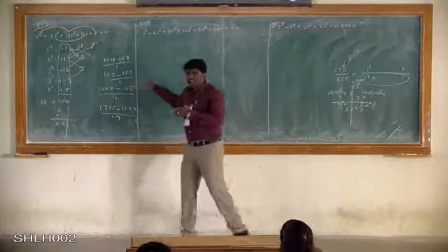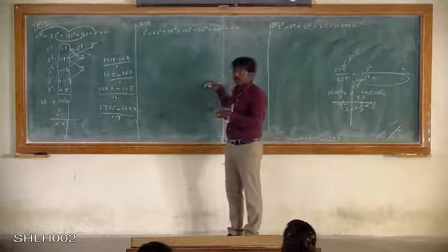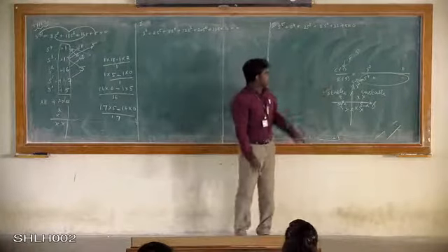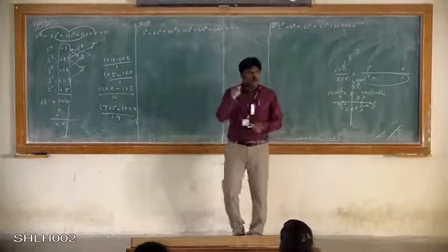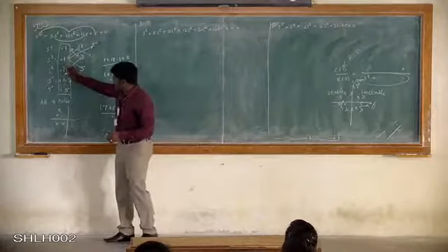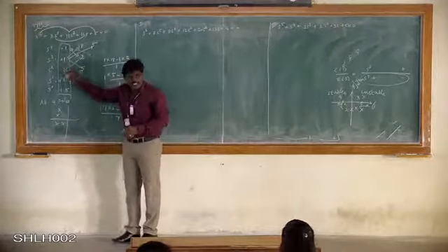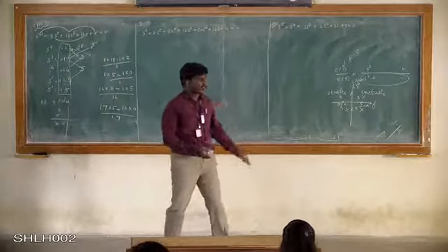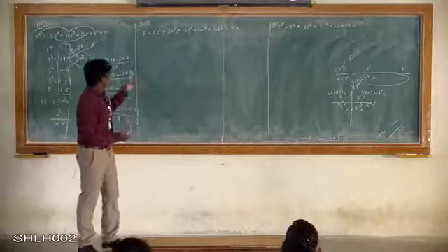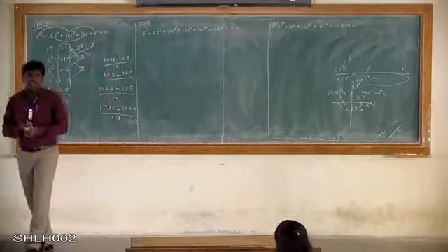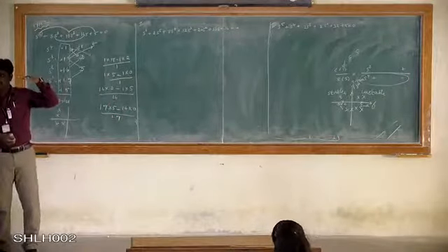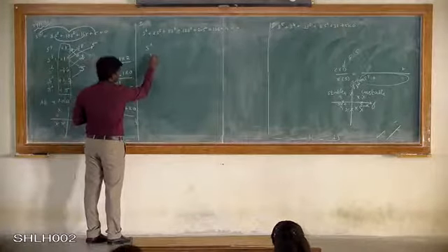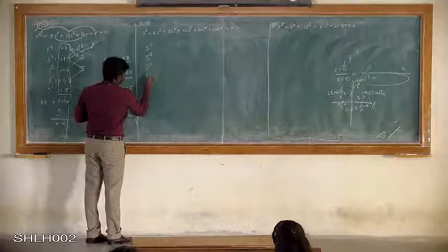So you will not be able to get the next row, right? So when you get a row full of 0, what will you have to do, right? This problem will explain that. The next problem will tell you about only one element becoming 0. In this particular case, instead of 16, if 0 comes, what will we have to do, right? So these are the 3 types we are solving. In the second type, we have got a 6th order equation, so we will have to start the values from s power 6. The table starts with s power 6, 5, 4,